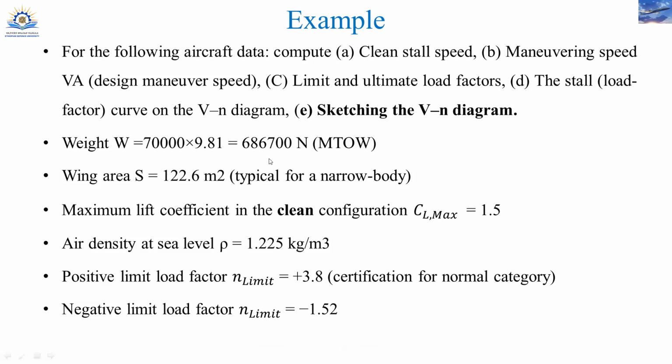Wide body and narrow body aircraft maximum lift coefficient in the clean configuration, CL max is given. Density at sea level given, positive limit load factor, N limit plus 3.8, and negative limit load factor is given, minus 1.52. So by taking this,